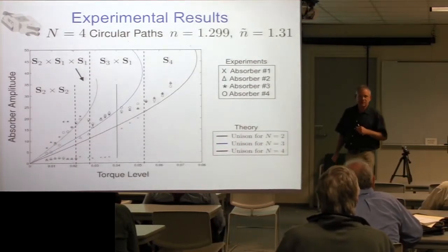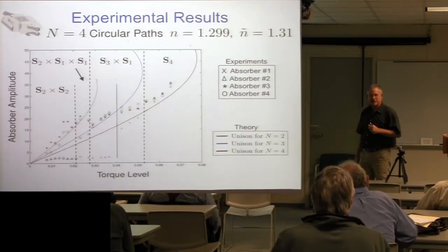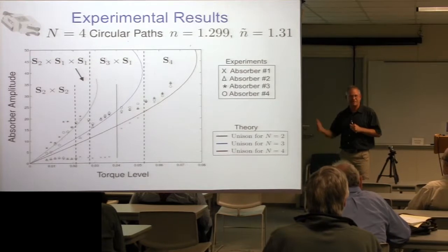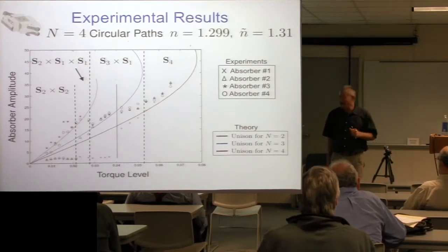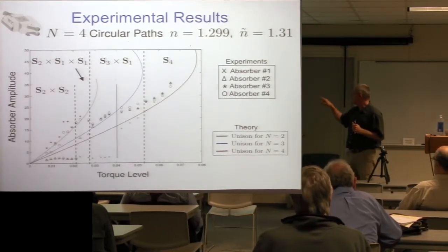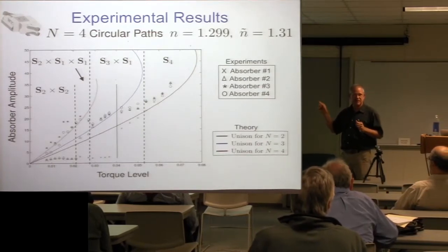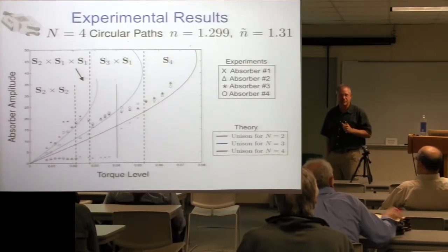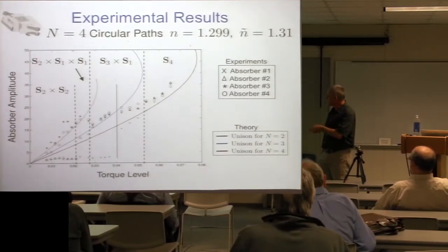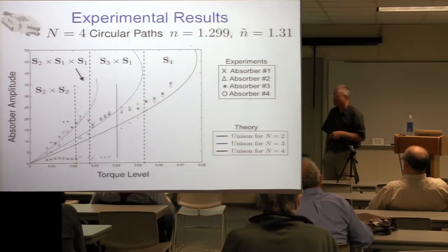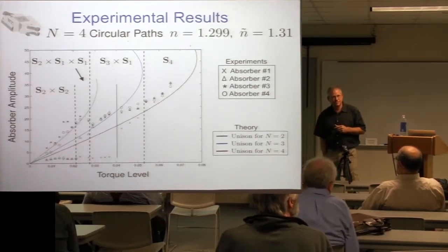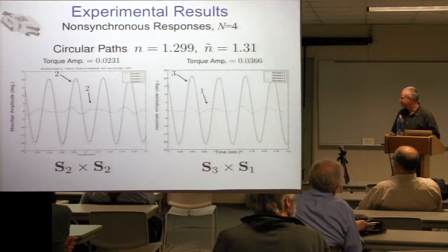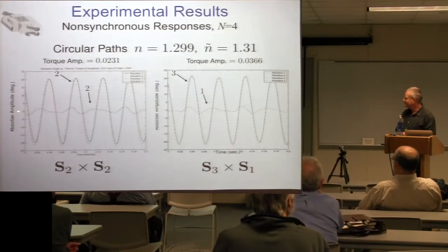Yeah, so I kicked around thinking about trying to figure out the coefficients in the normal form, but it's just a nightmare. If I were going to do it, I wouldn't do it for this system. I'd do it for a set of globally coupled Duffing oscillators, which is an equivalent system. I think that would be more tractable. But if you had dry friction, if one of them is in the lock mode, then you effectively lose one.